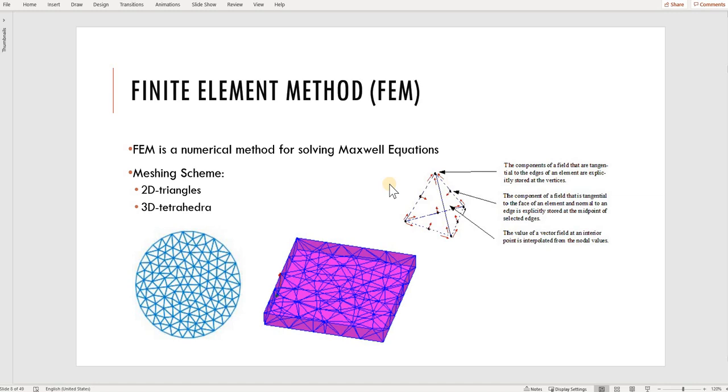As you know, the main function of HFSS is to derive and construct the finite element matrices by using the field equations and calculate the fields and S-matrices, which are related to the ports and excitation ports that we define.